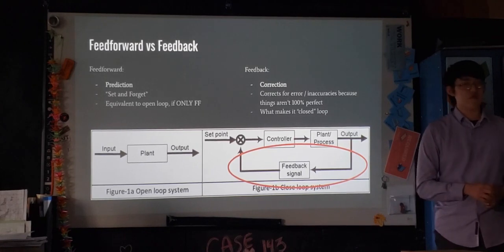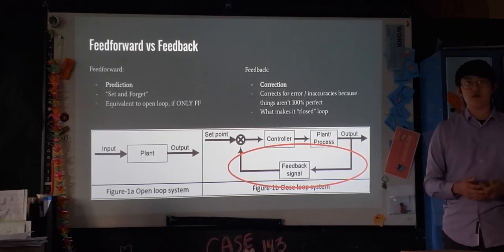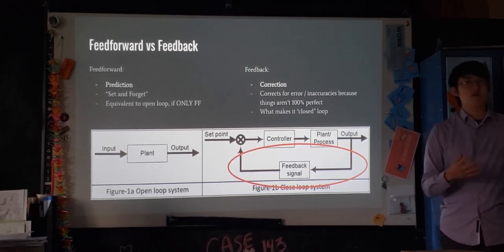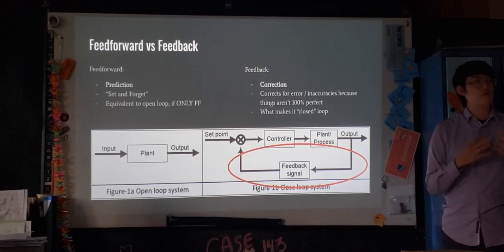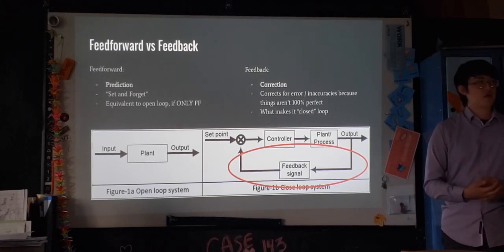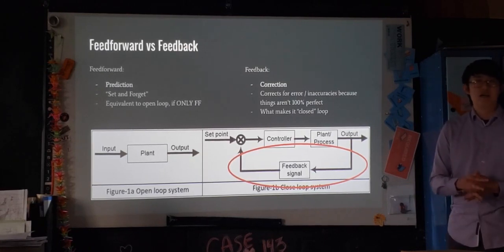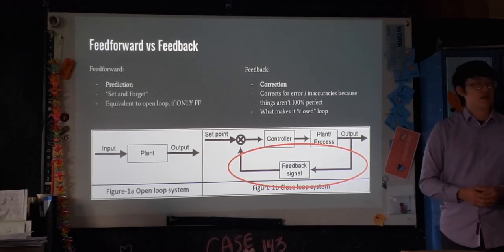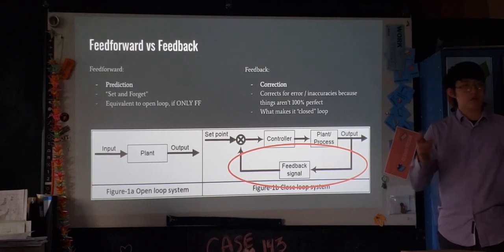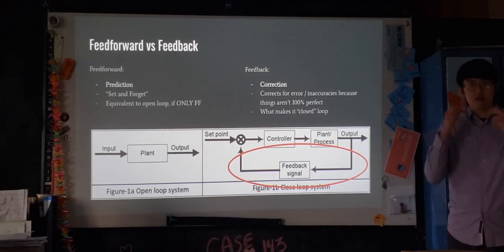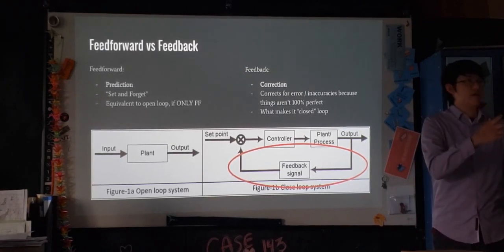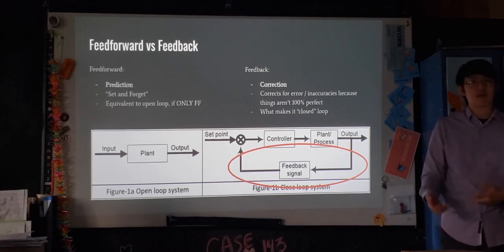As I said, feed forward constants need to know a little bit about your robot. And the only way to determine feed forward constants is through empirical, which means real life testing. That's what the SysID program is for. It is used to what we call characterize the robot. Characterize meaning get some constants out of it, run some tests on it.